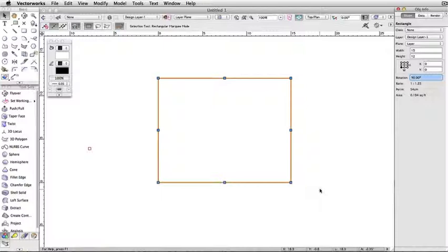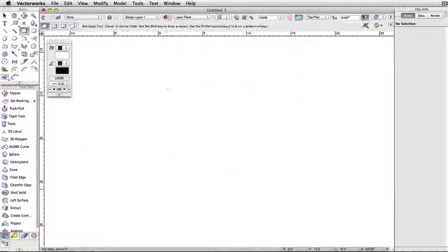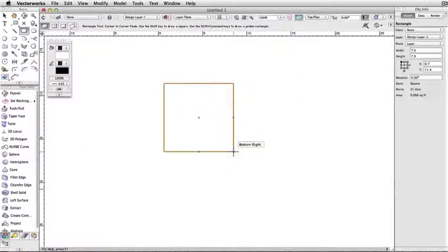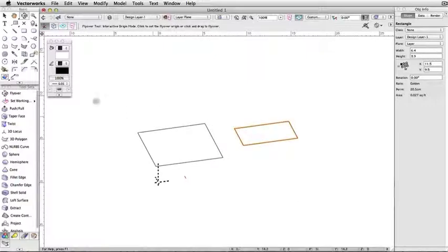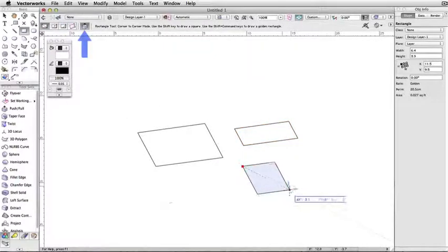Under this, you'll see details about the rectangle's ratio, perimeter, and area. The ratio will either display a numeric value or text if the ratio is square or golden. The rectangle tool also has a quick push-pull mode option that you will only see when in a 3D view, so any view other than top plan.